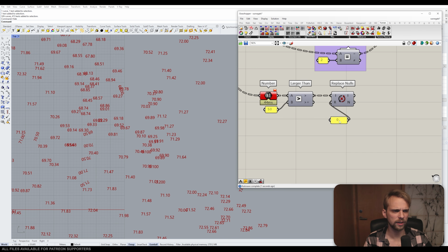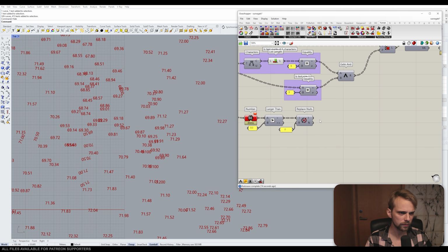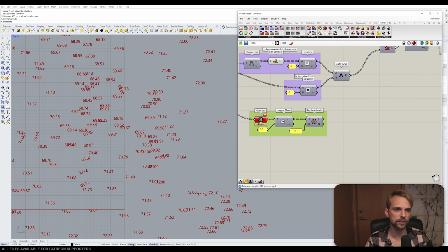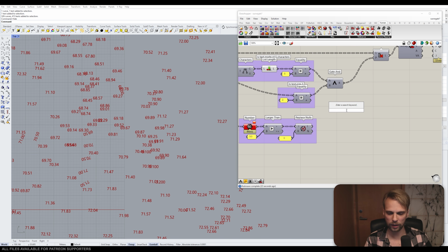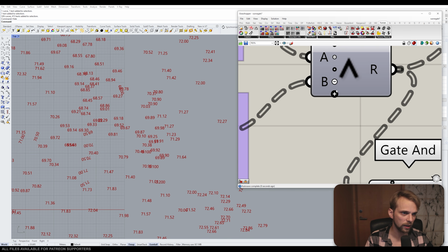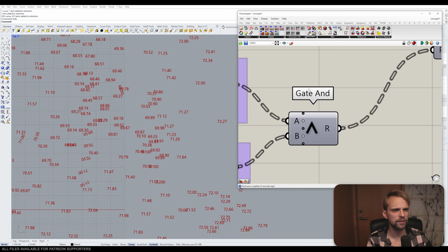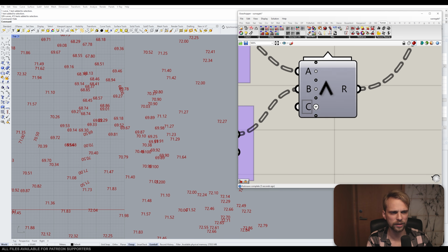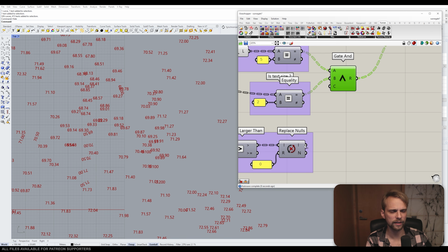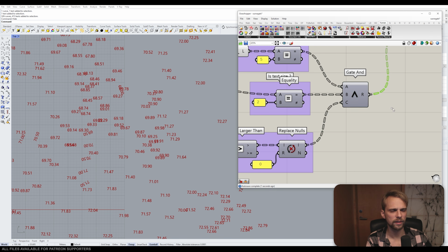In Grasshopper, as well as in most programming, false is no, right? So we either get true, or if it's a null, we just disregard it as false as well. Okay, with that done, now we need to add this check to the family. I'll write another AND gate. Actually, we can do it in a clean way. If you zoom into the original AND gate, you can just click the plus sign right here and add even more checks to it.